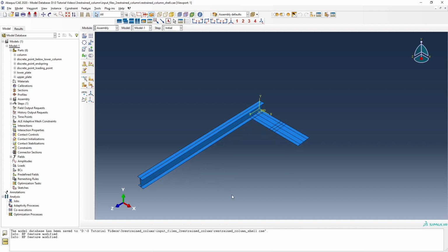and translate this part. So now we have this x y z type of coordinates, and our beam should have this y direction, which is the height direction of the column. So that can be obtained by rotation about x. So now let's rotate the instance. It will ask us to select the instance to rotate. So now we select this column, then accept, done, and then select an axis or start point for the rotation vector or enter xyz coordinate.